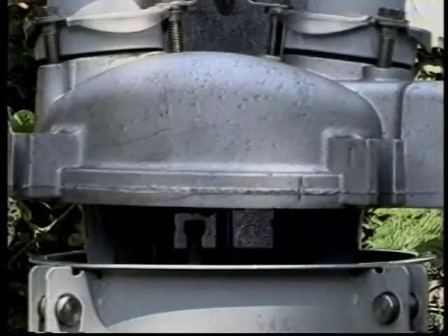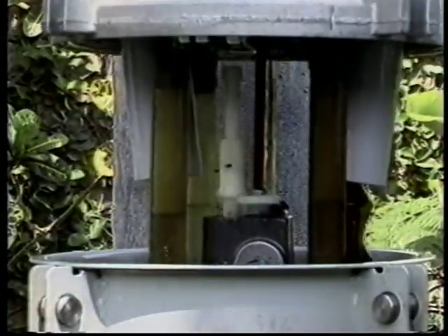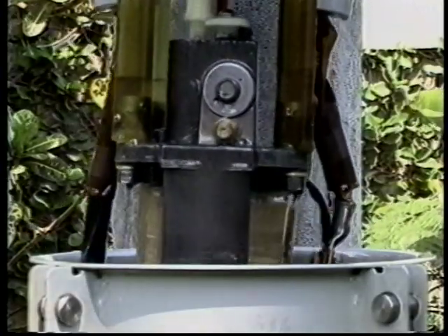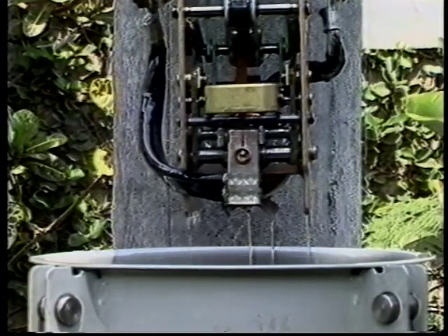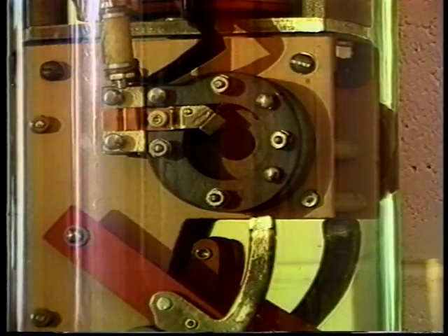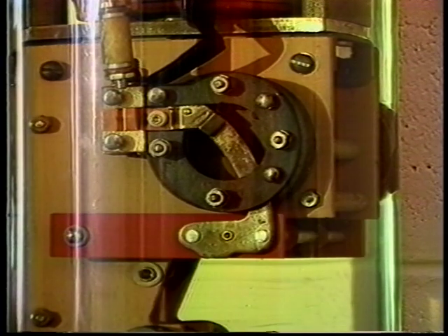General information. An automatic circuit recloser is a self-controlled protective device designed to interrupt and reclose automatically in an alternating current circuit. This is accomplished through a predetermined sequence of opening and reclosing, followed by the unit resetting itself or tripping into lockout mode.